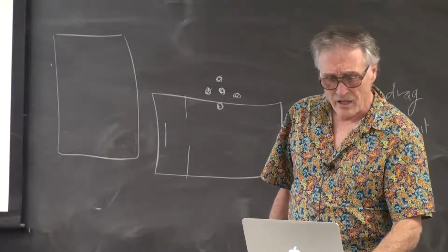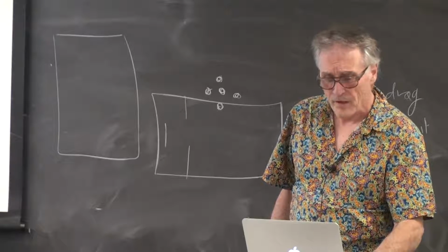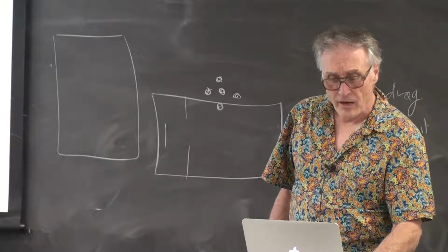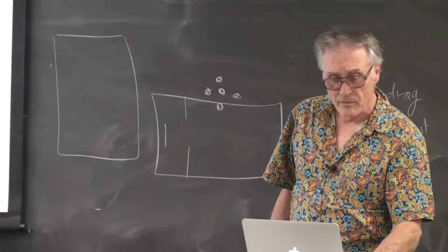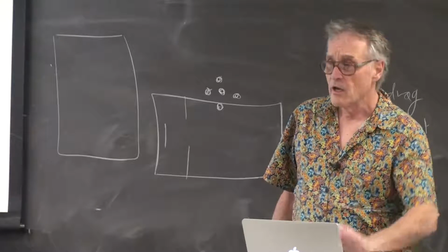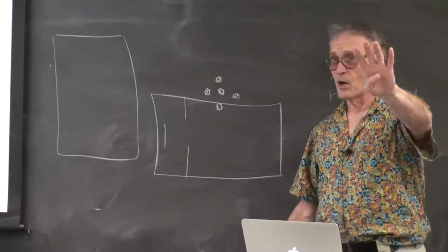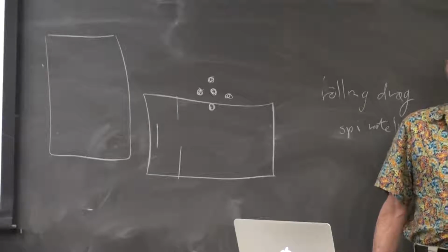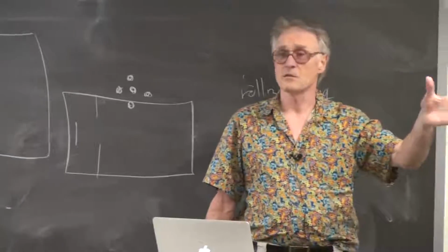When you do the TFT setup down in main, the very next thing you do after init and begin is set rotation. There are 4 rotation modes. You might experiment with the 4 and see if one of them is easier than the others.